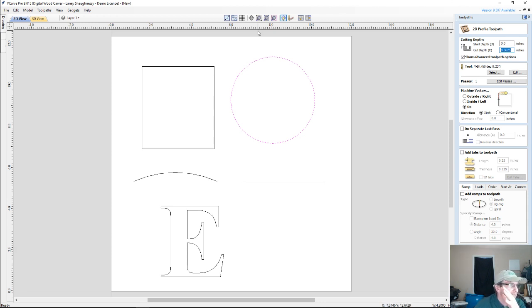When I am cutting the profile of a shape or an object, I am following that single line, and that is my profile toolpath. And that cut could be 1/16 of an inch deep. It could be 3/4 of an inch deep. It doesn't matter about the depth. We could either be cutting through the material or just doing a simple line outline cut with a particular bit.